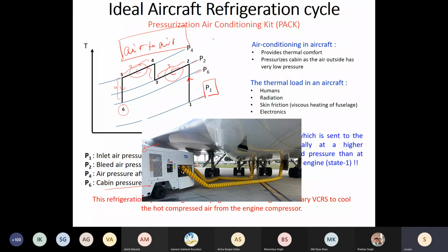The heat transfer which is occurring on the internal side, that is on the refrigerant side, that is tremendous. That is significantly high because it is all boiling condensation that is the major part of the heat transfer process. Whereas now over here you have air to air. So both sides you have air, and of course there is no phase change processes. So your heat exchange process is not as good as your condensers and evaporators in a residential AC. But what we are saving on is the size of the system.